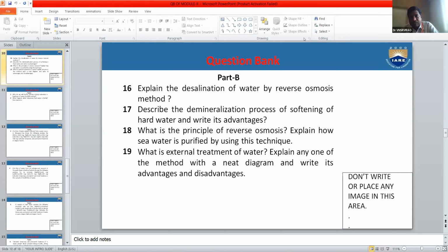And coming to the disadvantages, mainly the cost of the equipment is high, because we use both a cation exchanger and an anion exchanger. The resin cost is very high. It enhances the total cost of the equipment. And the second one is that the ion exchange process is applicable to remove ionizable impurities but not non-ionizable impurities, especially, for example, if you use turbid water. Turbid water cannot be purified by the ion exchange process. So those are the disadvantages of the ion exchange process.